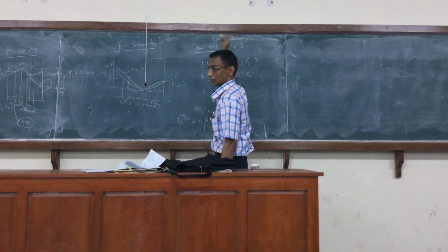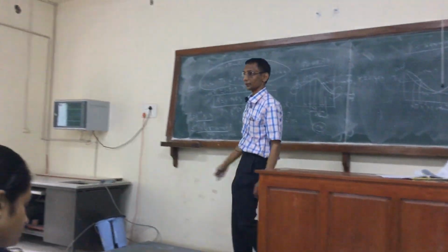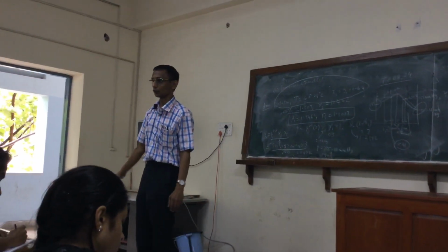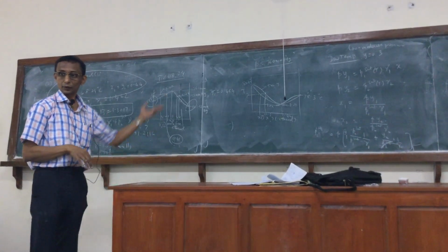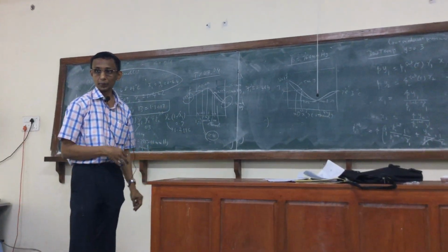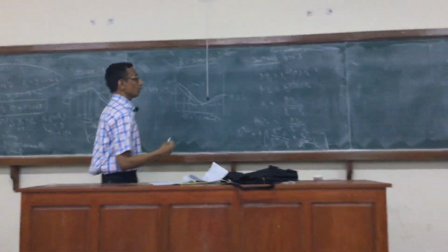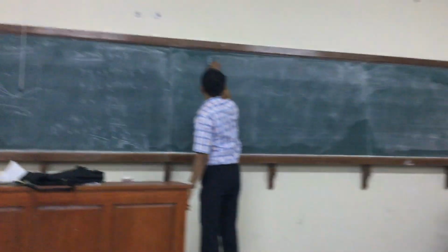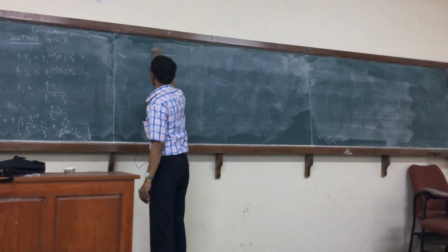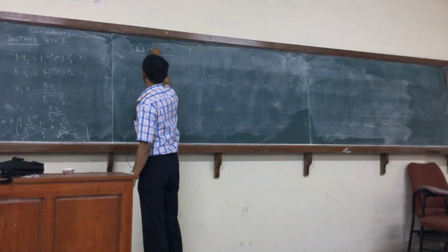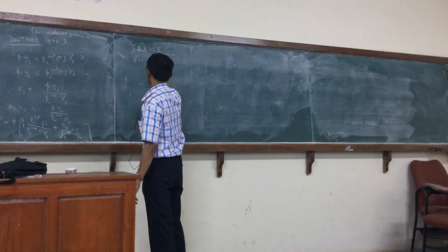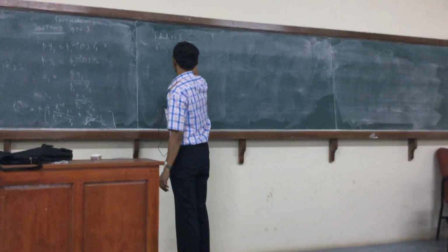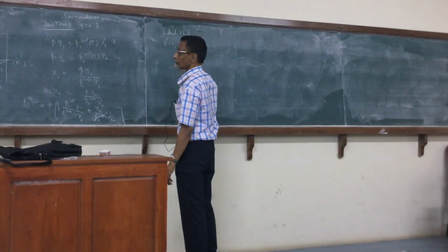When you go to high pressures, near the critical solution temperature and so on, the activity coefficient model cannot be used with accuracy. You have to use the equation of state approach for both the liquid and the vapor. Anyway, when we go to high pressure, the ideal gas mixture will break down. Right? So we have seen now an algorithm. To summarize, the ideal case is phi equal to 1 for the vapor and gamma for the liquid, gamma L equal to 1.